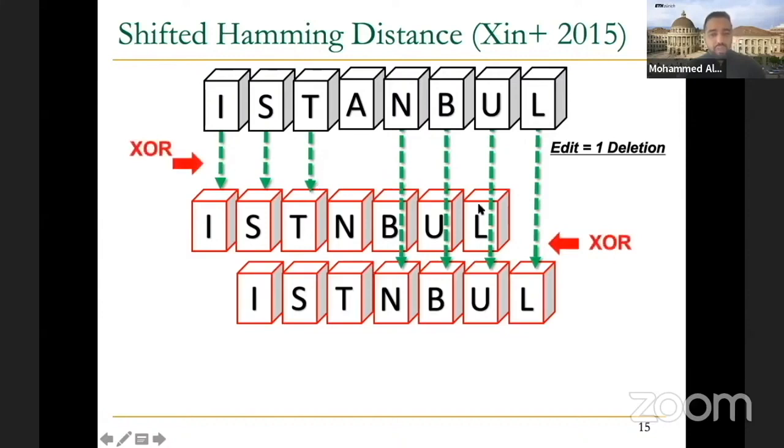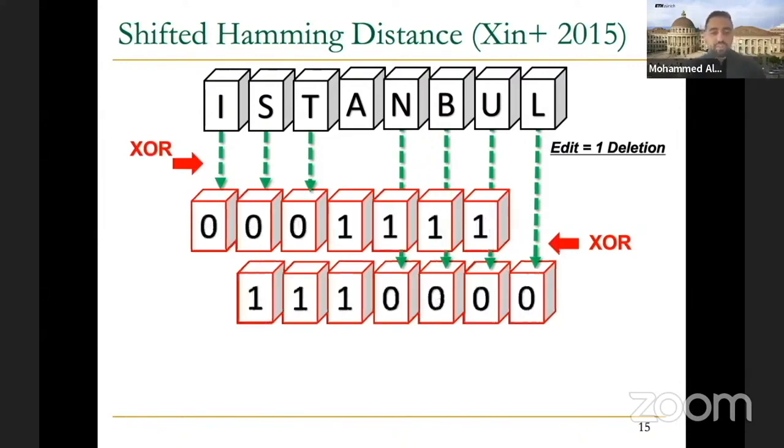So we have 3 here and we have 4 there. How can we do this in an algorithm or in hardware? The match operation we can do directly using XOR, right? And now these are the XOR results. If you convert the match into 0, because there is no difference. In the XOR operation, if the number of differences is odd, then you always get 1, right?